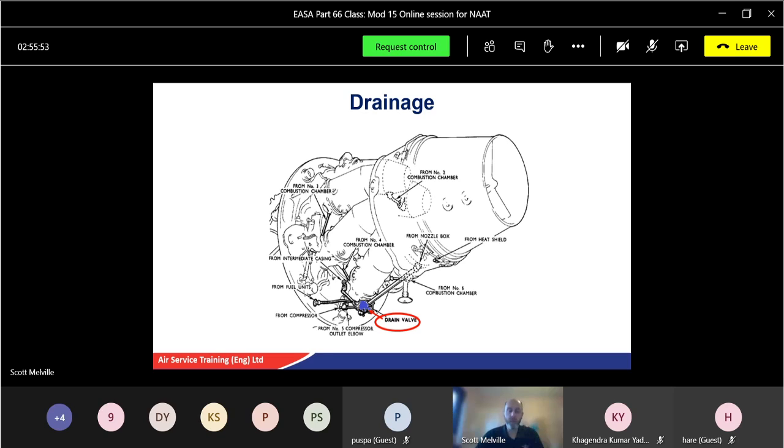If it starts dripping more and more, that's an indication that potentially that pump, let's say the fuel pump, is on its way out. I'll give you an example. Again, go back to the old cars. Water pumps have an indication drain: if you see water coming out of the water pump and dripping out, that's probably telling you that the seal or the bearing has gone, and they're designed to do that before it totally breaks down.